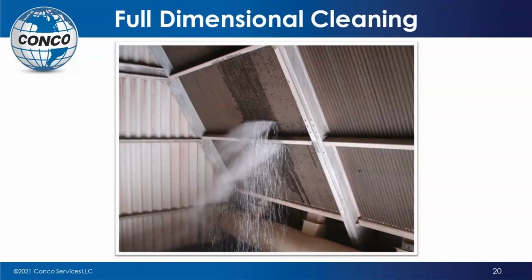Now, how do you know if you're getting a good cleaning? That's one of the questions we were always asked. How do we know if we need a second pass, or sometimes, if it's so bad, a third pass? Well, one of the things that you do is you go down inside the unit itself while the cleaning is going on. And you can see in this picture that the pressure of the water is still pretty significant as it comes through that unit. And when it comes out with this kind of pressure, you know that you've got enough pressure remaining coming through that unit that you've cleaned all those tubes. You're getting a good solid cleaning because the pressure's coming out on the other end.